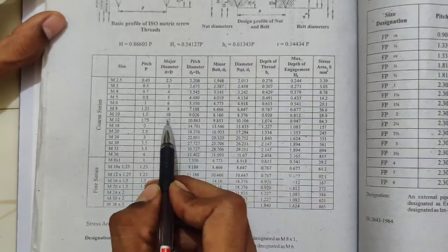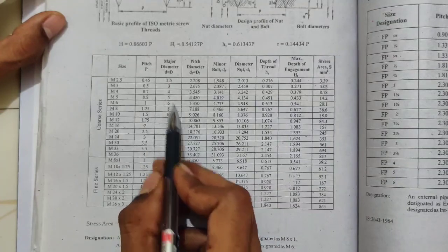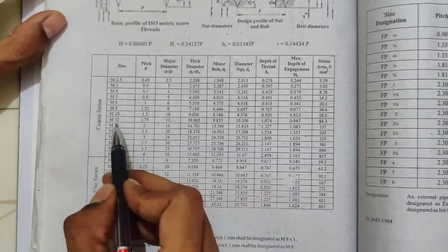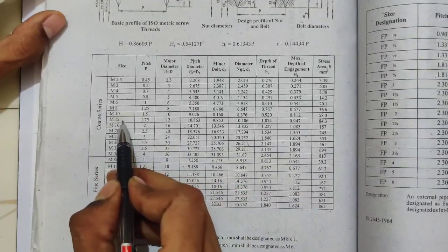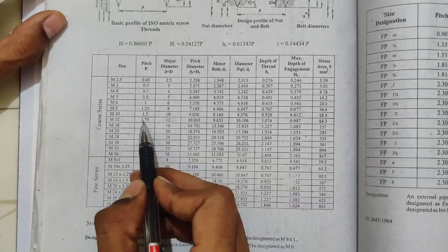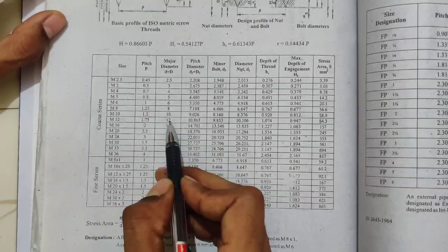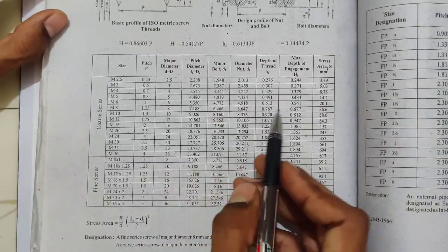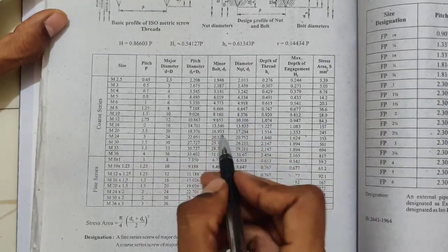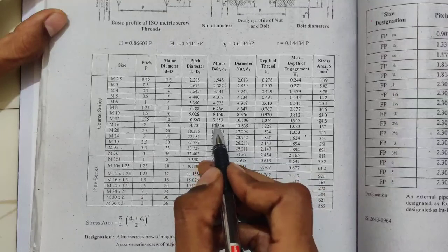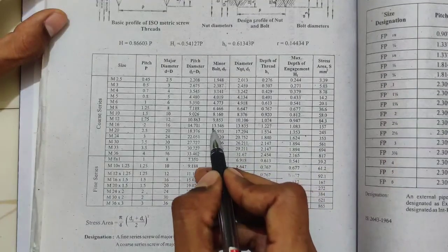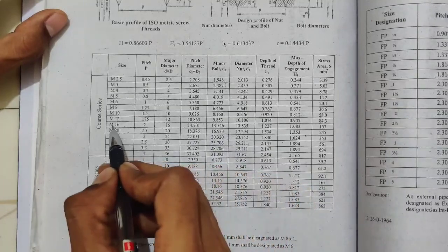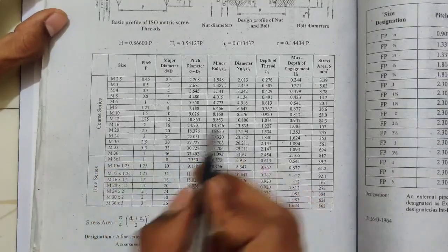Now let's go to the nominal dia. So this is the major dia, D is equal to D, major dia for 84.3 it is 12 and the bolt size is M12. So we can say M12 bolt is selected. It is having pitch 1.75, major dia is 12 and minor dia is 9.853. Or you can find this DC, the minor dia. Let's guess you have a minor dia of something like 12 point something. Then the next minor dia is this 13.546. Then you can call the bolt M16. Both methods you can use.